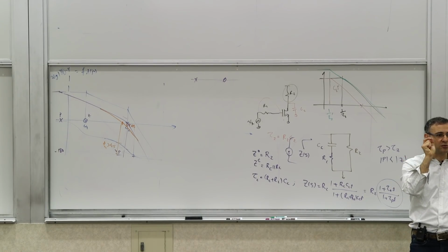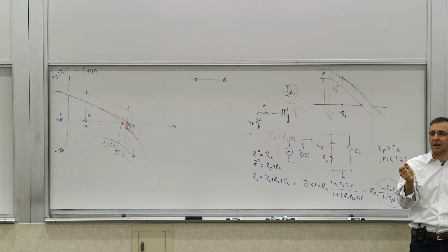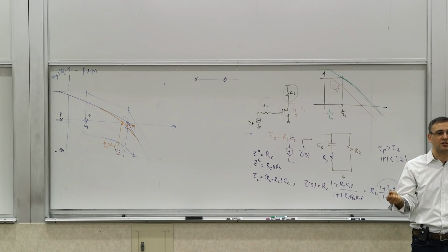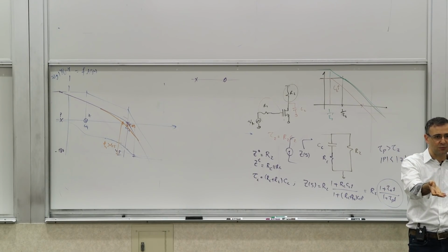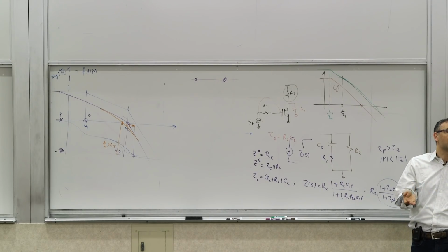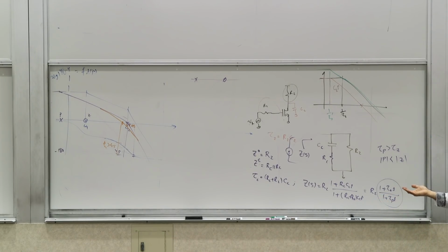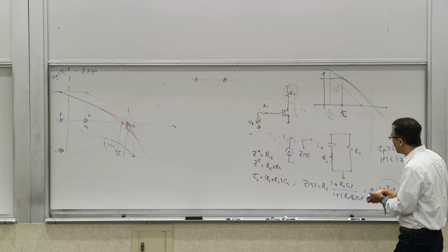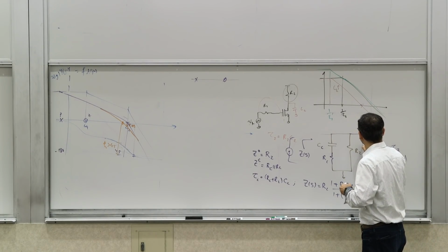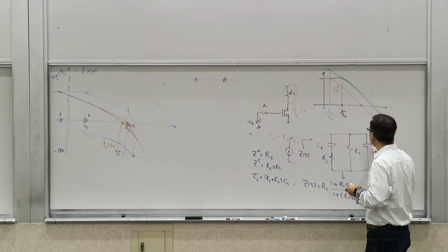You're relying too much on those being exact, but we know that they're not exact because the temperature changes, the parameter changes, one transistor may not look the same as the other one because the doping levels are different, things of that sort. So there is so much you can do with this thing. The next level up really is to add an extra capacitor here, right? You can do a C2.